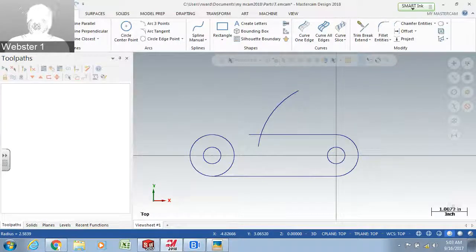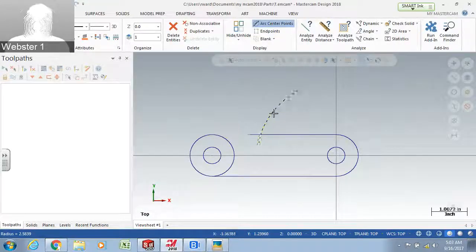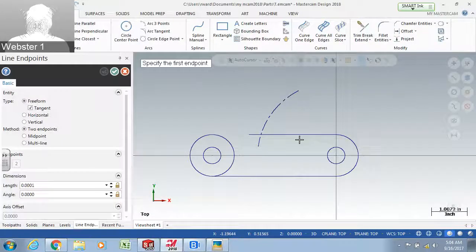And then let's change that to a construction line, or a center line even would be probably a better word. So if we click on this, we can come into here and we can say that it's a center line. So we can change that attribute of that one entity. Now there's arcs below and above that, and they've got some lines coming at angles. So let's change this back right now to center line so that everything we draw for a little bit will be center line, and we go to line commands.